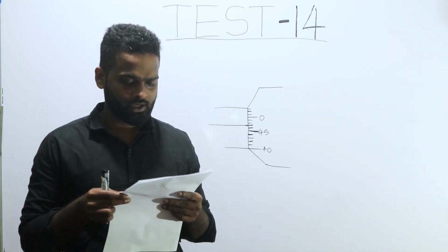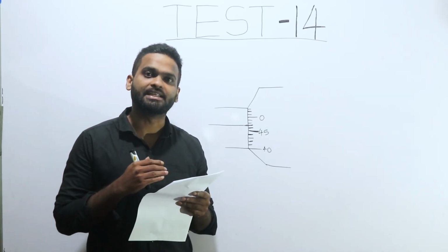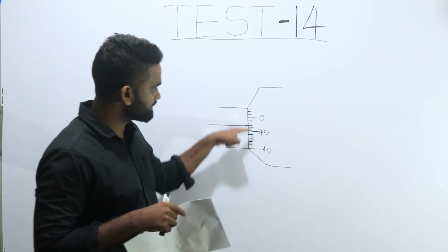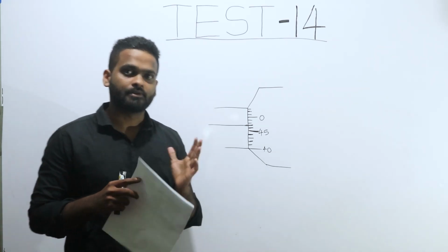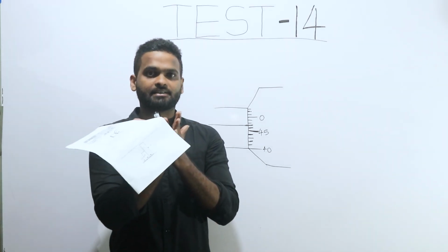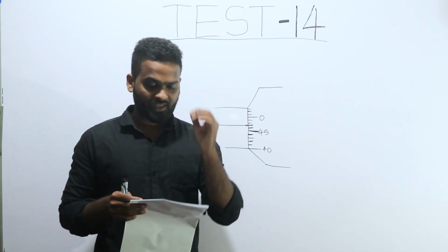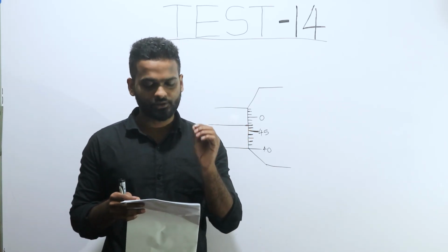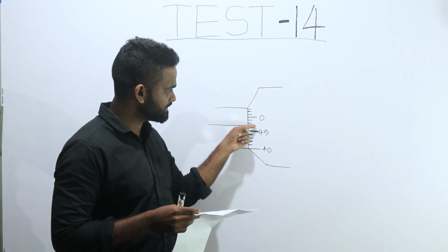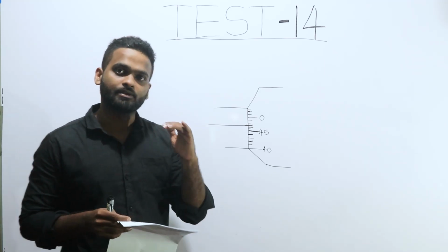Okay, so they have given a sketch of the screw gauge. The circular scale is given and the midline of the linear scale. So this is the circular scale and this is the midline. They are asking for the zero error. When the spindle and anvil faces touch, if the micrometer screw gauge is not erroneous, this midline and the zero mark of the circular scale should coincide. But if it doesn't, there's a zero error.